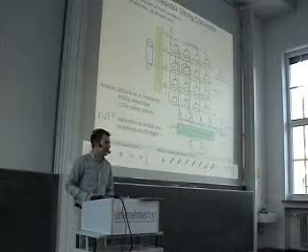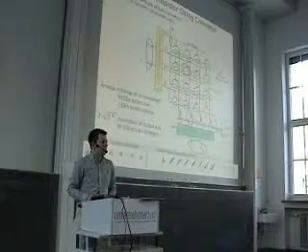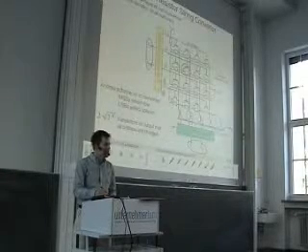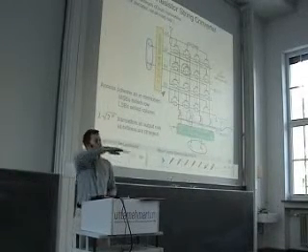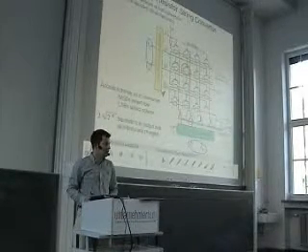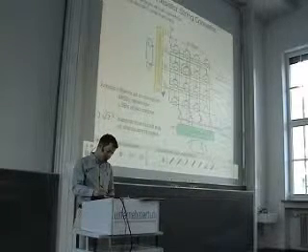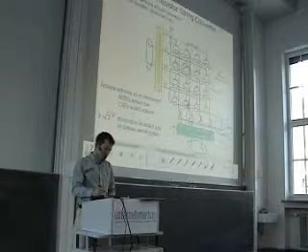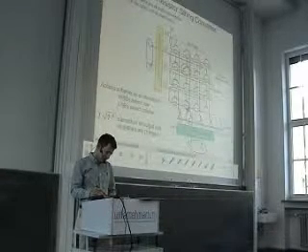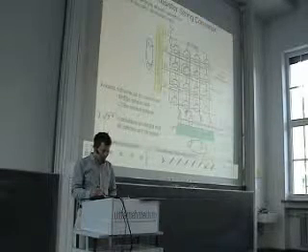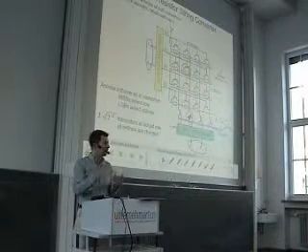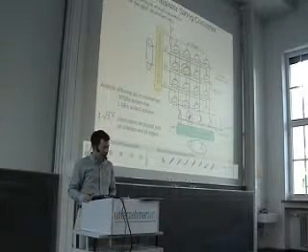So this is an access scheme as you probably know it from memories. In memories we call this a word line. Then we turn on one word line, enable all cells in the respective row. We call this a bit line. So the memory content is applied to this bit line, and then we have a column decoder and a multiplexer that selects one of a set of bit lines and connects it to the output.